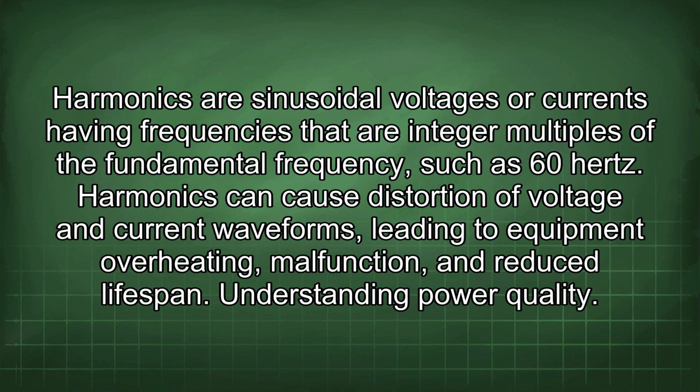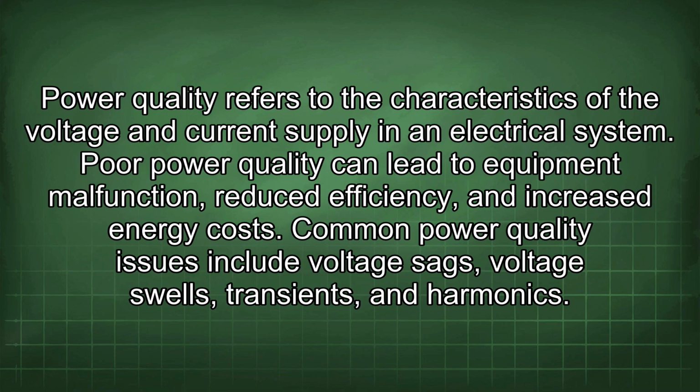Understanding power quality. Power quality refers to the characteristics of the voltage and current supply in an electrical system. Poor power quality can lead to equipment malfunction, reduced efficiency, and increased energy costs. Common power quality issues include voltage sags, voltage swells, transients, and harmonics.